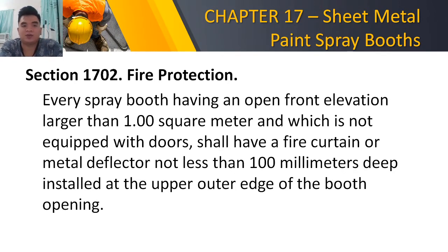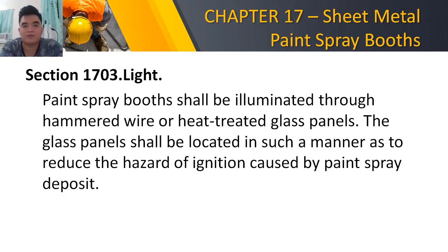Section 1702, fire protection. Every spray booth having an open front elevation larger than one square meter and which is not equipped with doors shall have fire curtains or metal deflectors not less than 100 millimeters deep installed at the outer edge of the booth opening.